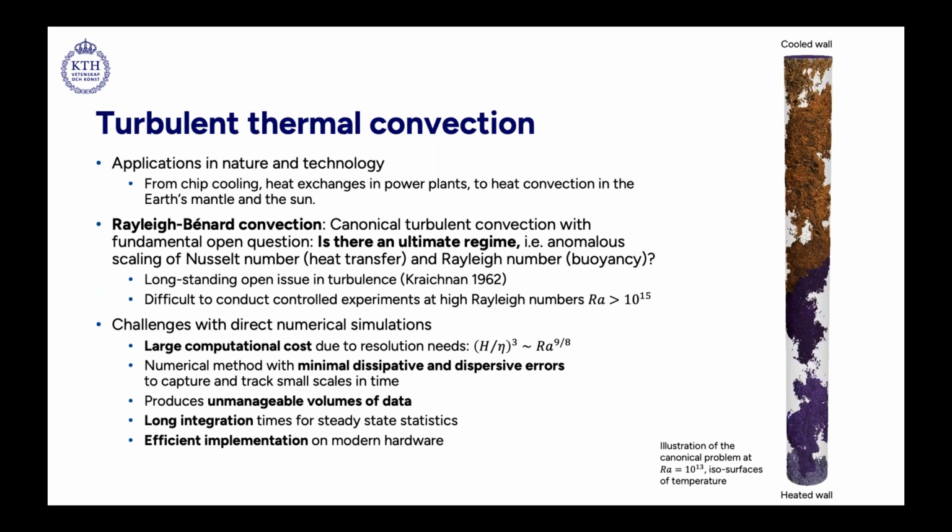The challenge is that simulation will have a very high cost because the resolution relates to the Rayleigh number to the power of 9 divided by 8. So it's going to be very large problems that you have to run. The second problem is that you need good numerical methods and you have to be able to capture and track small scales over a long time period, because you also need long time integration to get steady state statistics, so very long simulations. And of course, if the problem size is large, you're going to create a lot of data that you need to handle in a certain way.